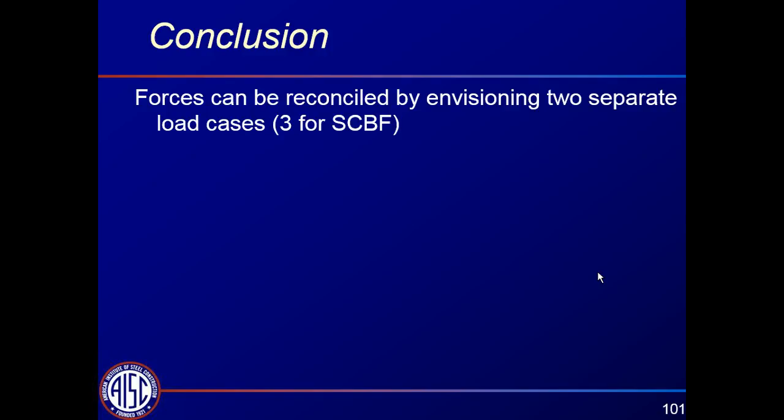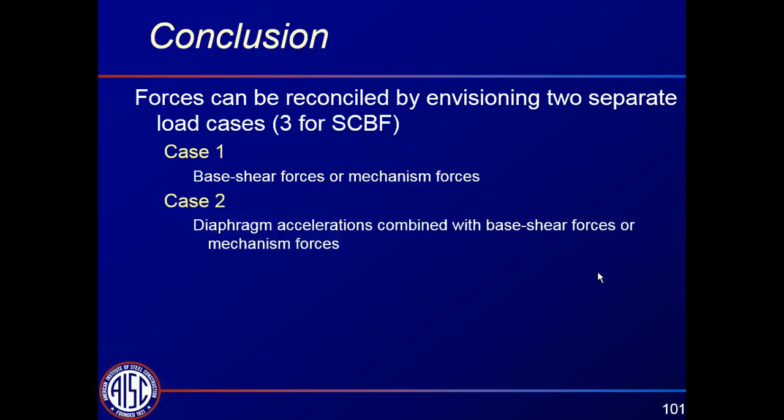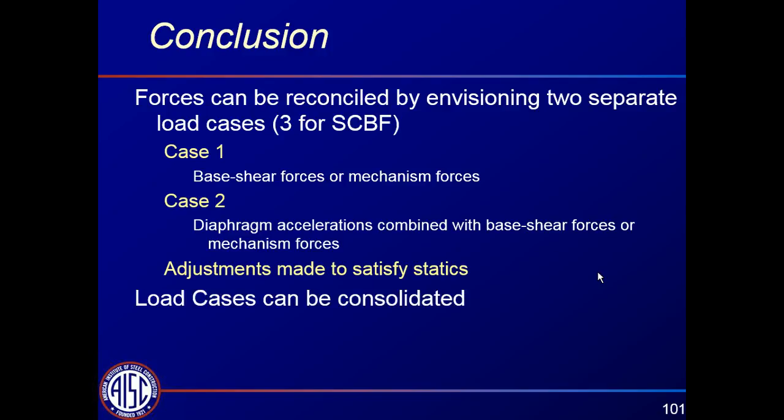There's a third one for the special concentrically braced frame. So case 1 has the base shear forces or mechanism forces, depending on what type of system it is. And then case 2 includes the diaphragm accelerations, with some of the mechanism forces and some adjustments made to satisfy statics. Load cases can be consolidated for simplicity.